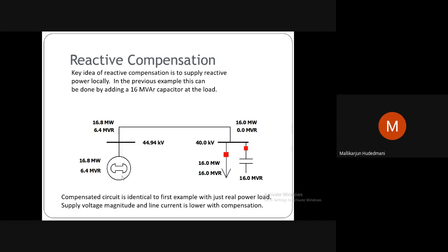The reactive power that the synchronous generator is pumping is just the drop happening all along the reactive path of the system. So therefore, if the line reactance were ideally 0, definitely this wouldn't be injected. It is injecting at 1 pu only, meaning frequency 1 pu and power factor 1. So if this capacitor is eliminated from the simulation, what would happen? Definitely you will find 16 MVAR, which is the load here, and the drop all along the path is 6.4. 6.4 plus 16 is 22.4 MVAR. This generator would have pumped that to the grid.